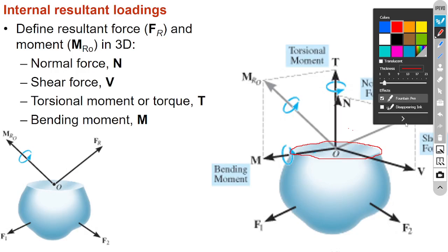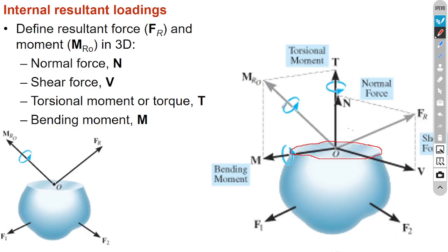But if we substitute into the stress expression the total area at the cross section, initial area for engineering stress, true area for true stress, and this is the component of the resultant of the atomic bonding forces, the stress is going to be the average stress.